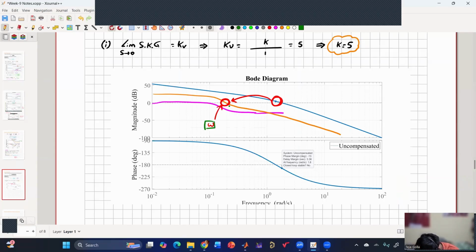So that the phase corresponding to this omega, this is my phase margin, right? So this requirement is met. So I have to choose that omega so that at that omega, the phase corresponds to my phase margin, because now this is my gain crossover frequency. Because this is my new gain crossover frequency, my phase margin will occur over there.